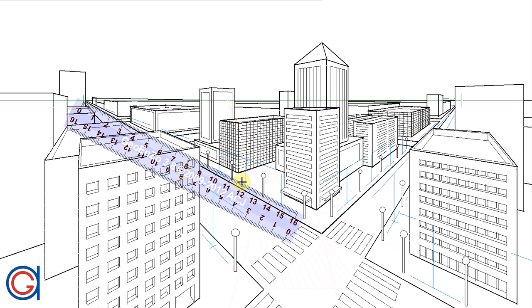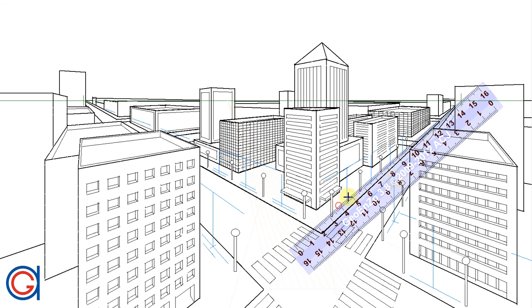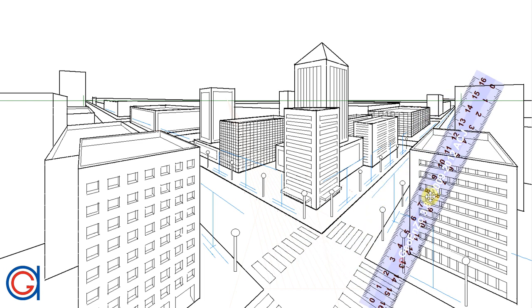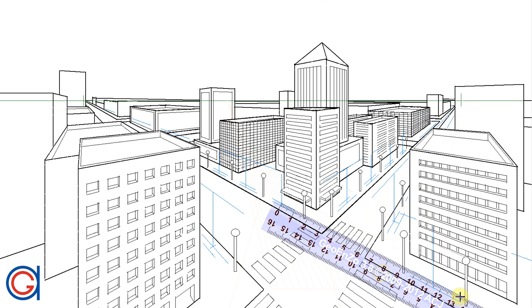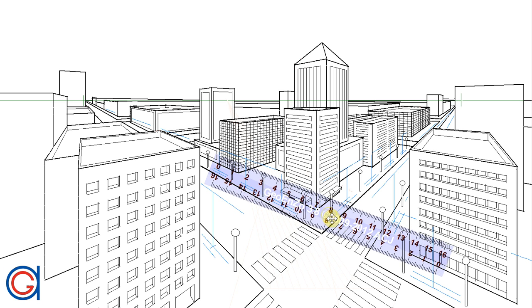So now we are going to draw two parallel construction lines each side of the previously drawn tree baseline, where we are going to locate the square tree wells. We complete these square tree wells by drawing perpendicular lines each side of the tree base, or the tree bases.